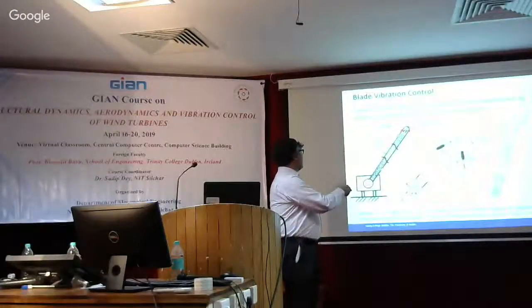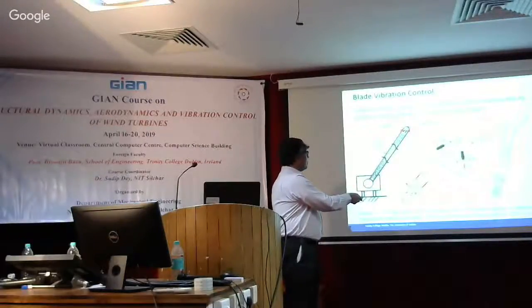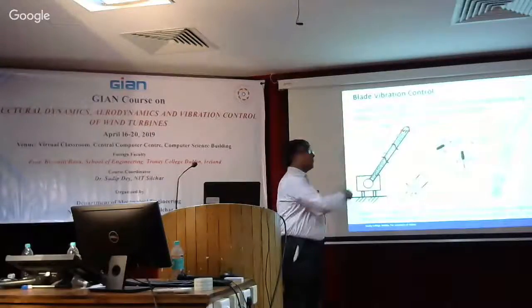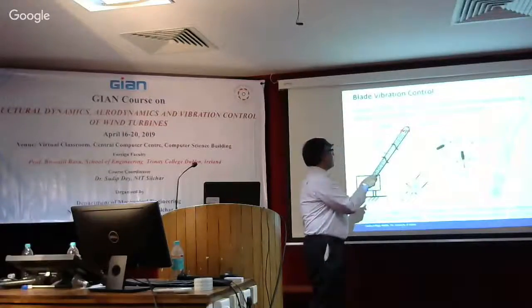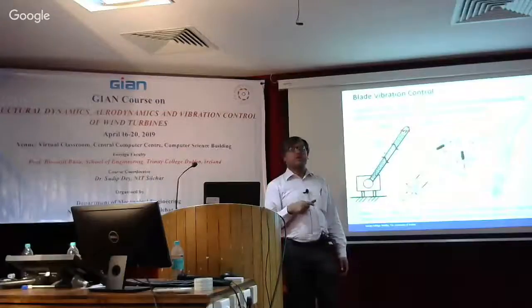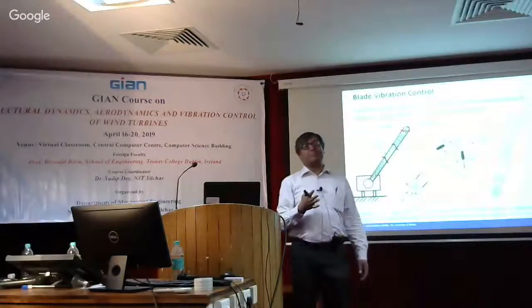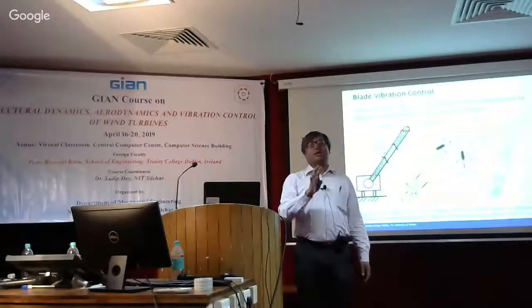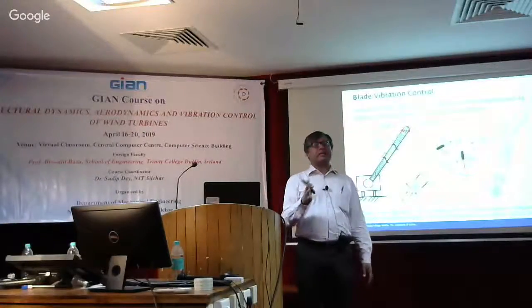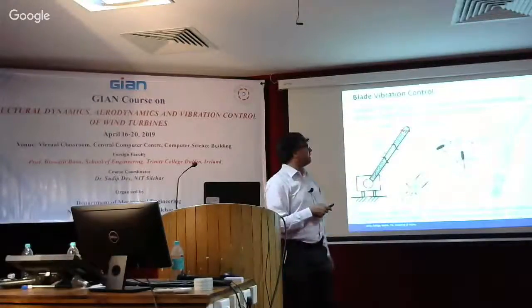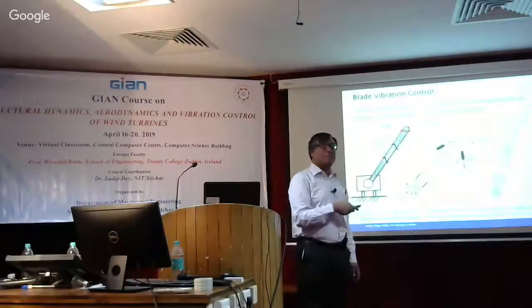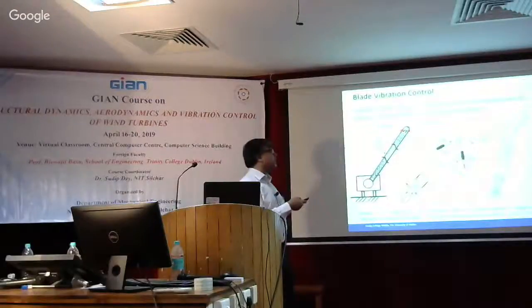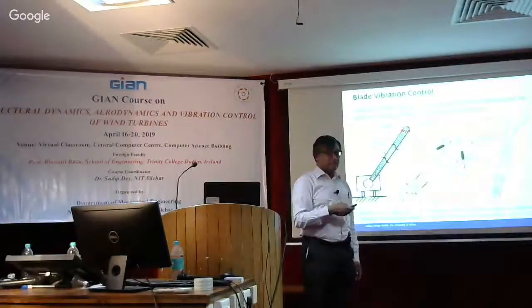And the cable of that active tendon is connected at the hub or the nacelle. So there's no force transferred on the plate, because they don't want to touch the plates much. And the effect of this is that you can have an actuating force here. The advantage is that this can also control the low frequency zero mean type of response. And in the edgewise direction, gravity is a significant load, and including that, other low frequency loads are there. So this is quite successful in controlling that, and that's why this is very attractive compared to any other controllers. And I don't think there's any other controller which can do the same thing this one does.